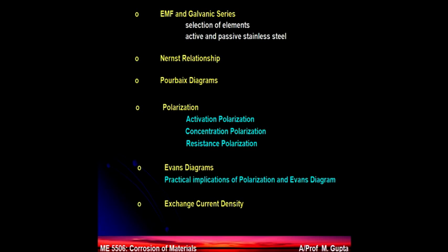Maybe you coat your material completely. If it is in the passivation zone, you know that your material has a tendency to make an oxide layer, but the Pourbaix diagram will not tell you whether it's a good or bad oxide. So in that situation, it will make an oxide, and you check whether the oxide is good or not. One very simple way is to see whether it is gaining or losing weight continuously.